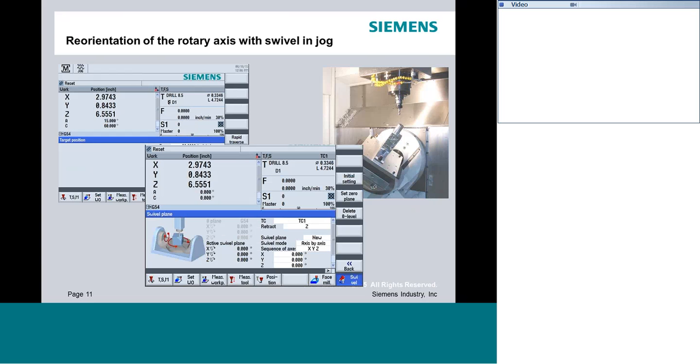From there, we're going to start to explore some key features that have been developed specifically for managing 5-axis machine tools. For our instance, we're going to look at the Swivel Cycle. Swivel Cycle is a way for us to start manipulating where the rotaries are in space, but based on data that's more closely related to what our part program will actually be doing.